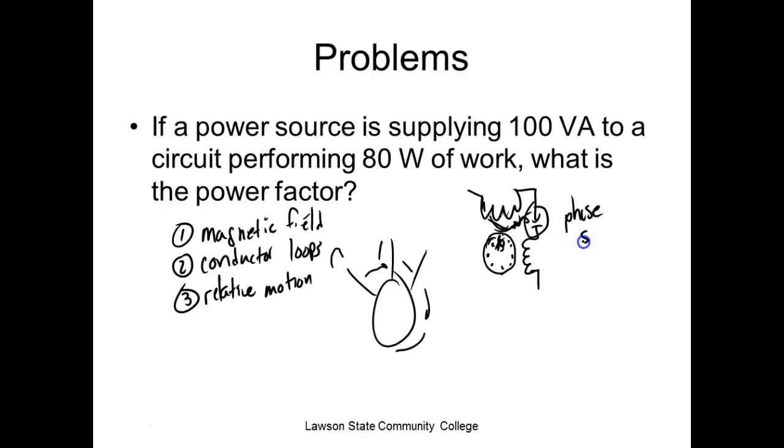It creates a phase shift. So now that the single phase motor will do what? It'll turn. Now, once something's in motion, it's going to stay in motion. So most of the time, this will be a very cheap wire. It won't be very much, and they'll put what they call a centrifugal switch in here. So when the motor comes up to speed, it'll kick out the start winding. You don't need the start winding except to start the motor. And y'all can hear it click, click.